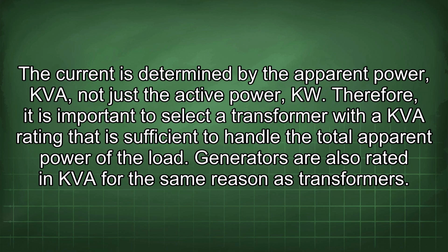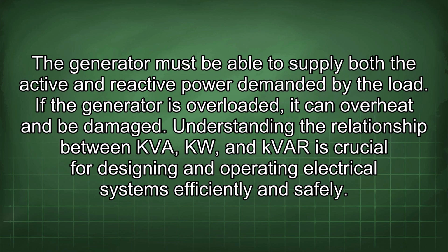Therefore, it is important to select a transformer with a KVA rating that is sufficient to handle the total apparent power of the load. Generators are also rated in KVA for the same reason as transformers. The generator must be able to supply both the active and reactive power demanded by the load. If the generator is overloaded, it can overheat and be damaged. Understanding the relationship between KVA, KW, and KVAR is crucial for designing and operating electrical systems efficiently and safely.